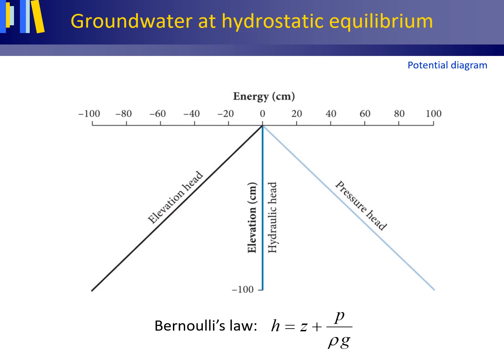When we descend into the groundwater, the pressure head in length units at different elevations is linearly related to the length of the water column above the elevation of interest. Pressure heads below the water table thus are positive, and the relation between pressure head and elevation can now also be drawn as a line under an angle of 45 degrees for equally scaled axes, but in a different direction than for the elevation head, as shown in this figure.